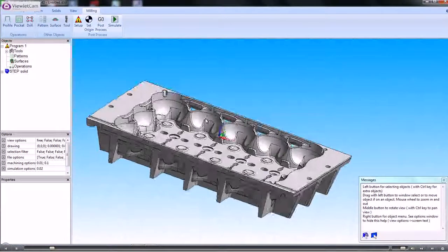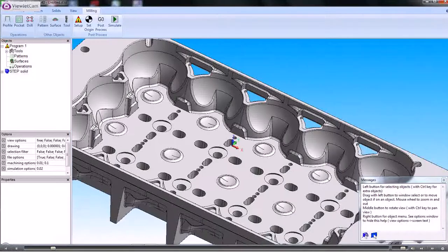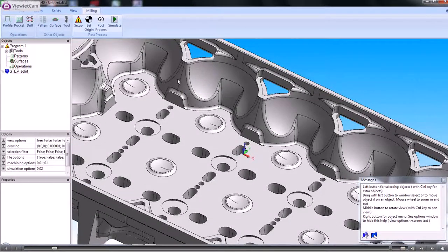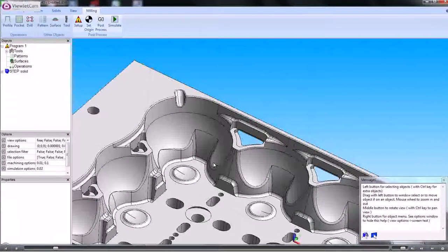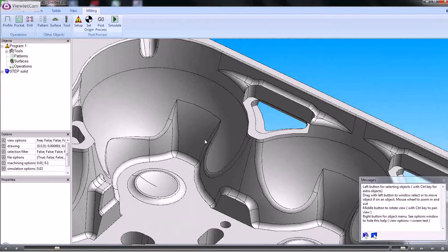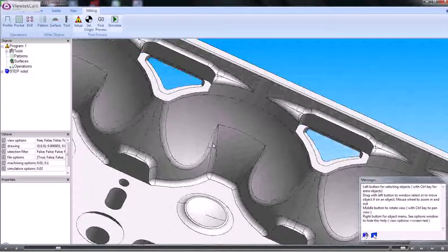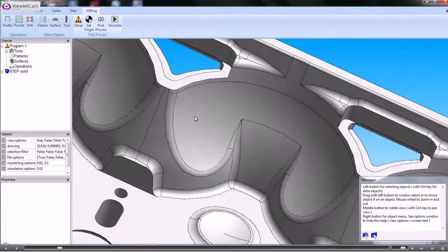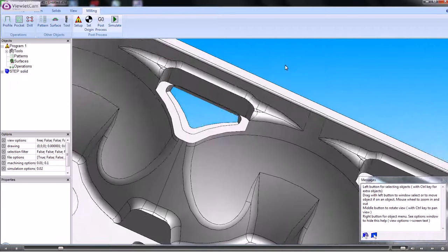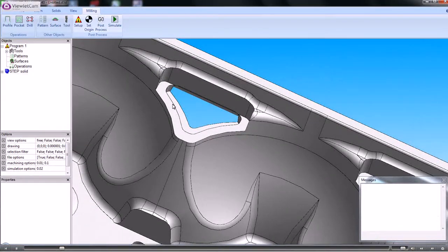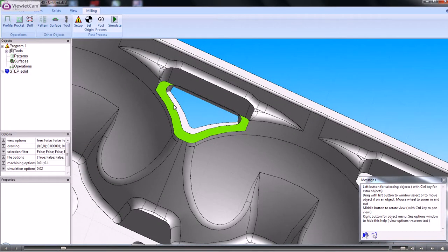Okay, so that's the file there, and we need to machine just these pads here. Now if we wanted to machine those and select faces, what would happen is if we selected that face, that would give us an enclosed shape which wouldn't be what we wanted to machine. So what we'll do is we'll pick edges and create a sketch made up of edges.